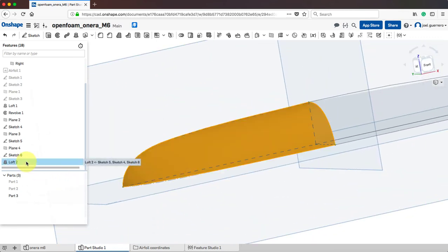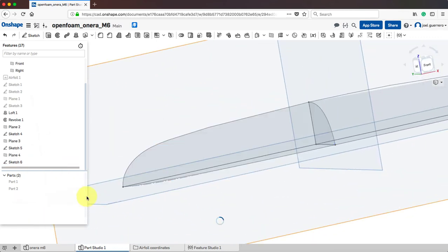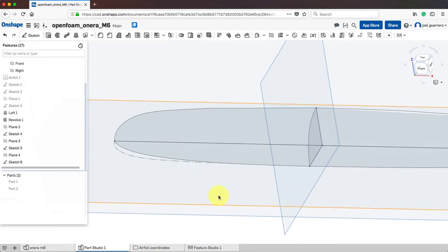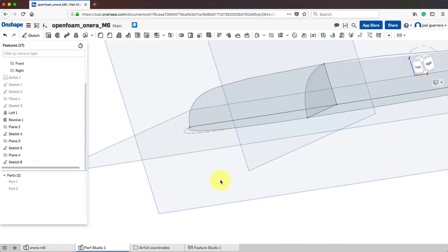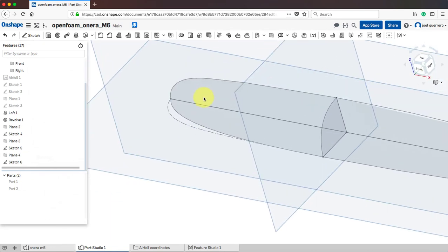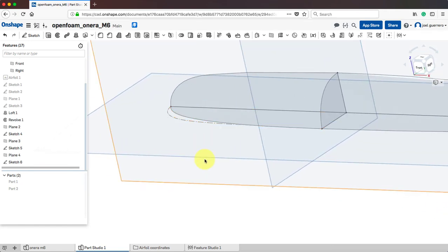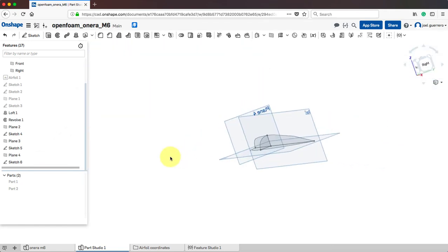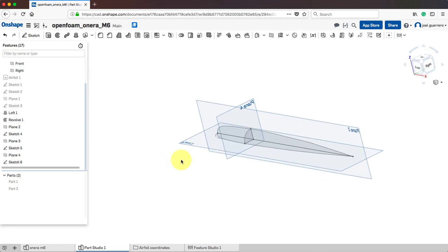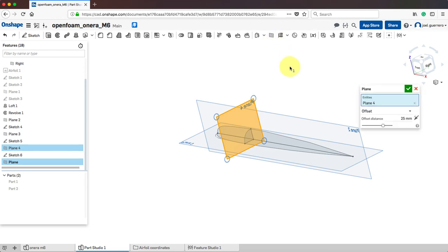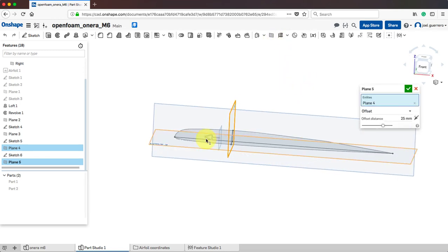Okay, so let's erase that one again, and let's add another shape somewhere here to have more control of what we're doing. Remember, you need to control your support geometry, the reference plane. So click here, there, and let me create a plane.